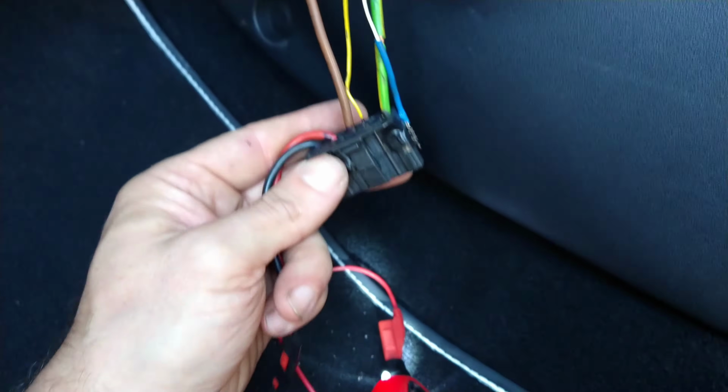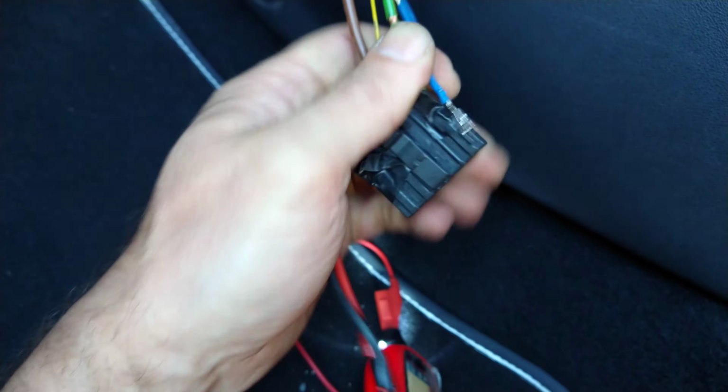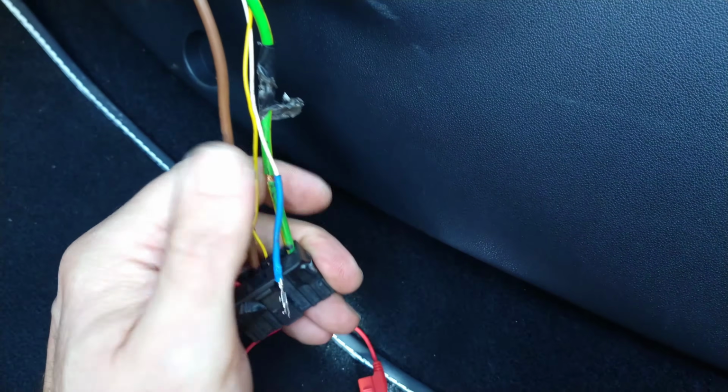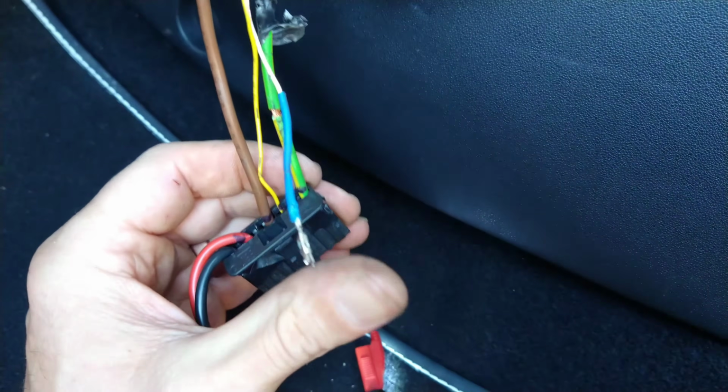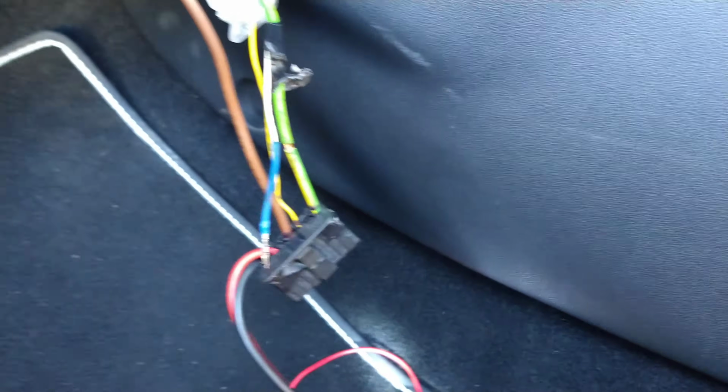I've peeled back the wires a bit and I can see that this pin here wasn't actually in all the way. It didn't come to the end, and when I just touched it and took the tape off that was around here, it came out. But I still should have a ground on this wire. So I think if we give that a ground, it's going to start working.